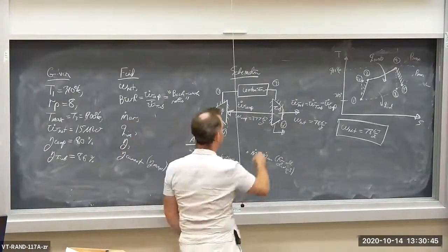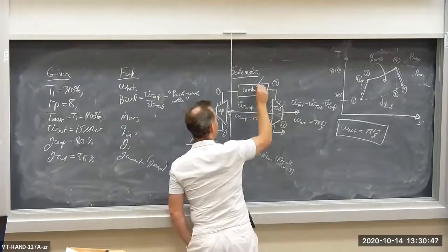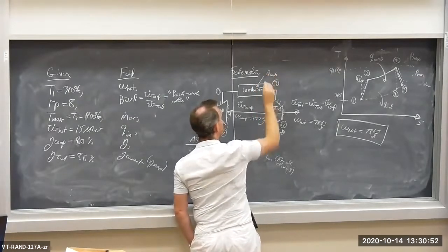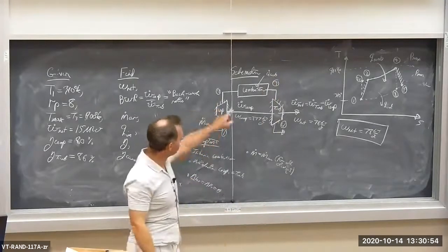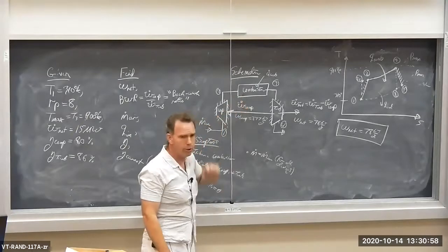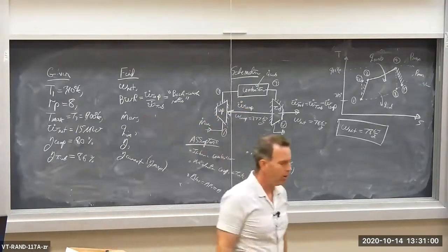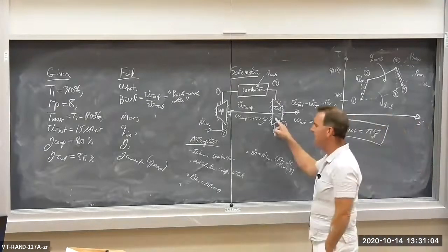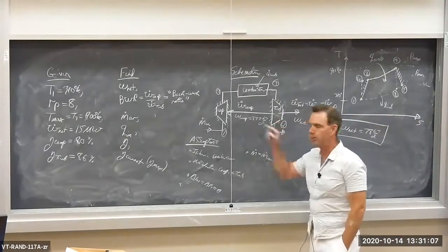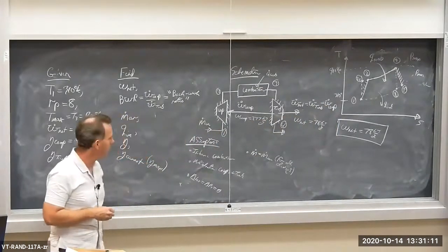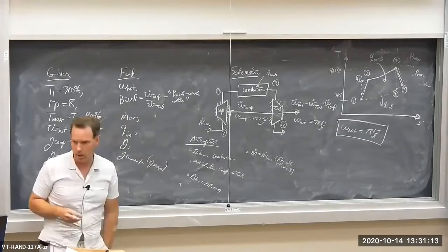The reason is because we are adding fuel and therefore heat, Q dot combustor. We're actually adding fuel into the combustor, not very much. By mass, maybe 1 or 2% of the airflow. We're adding a little bit of fuel and we're burning it. So the mass flow rate through the turbine is a little bit larger than the mass flow rate through the compressor, but we're not worried about that. We're going to assume the mass flow rates are constant.